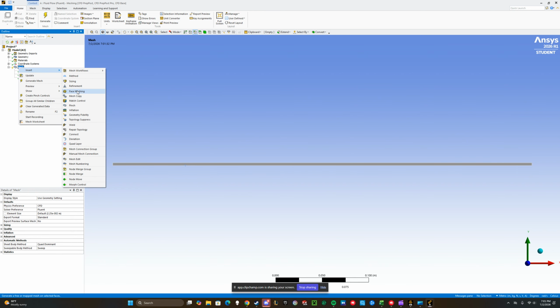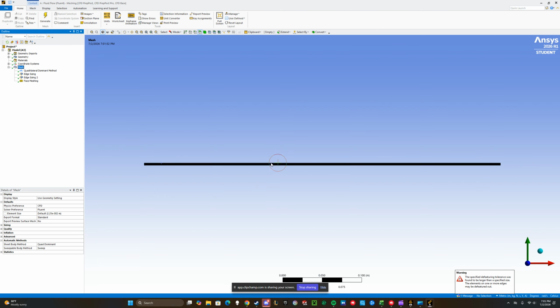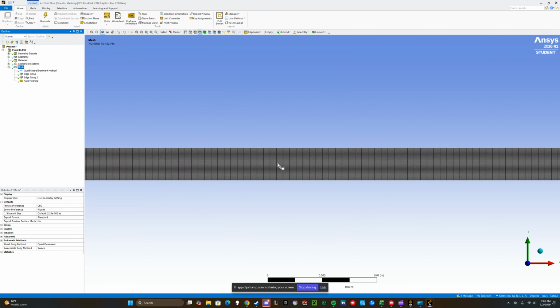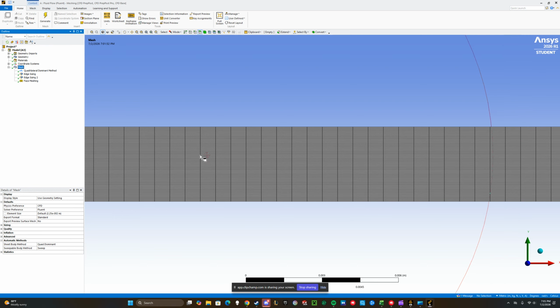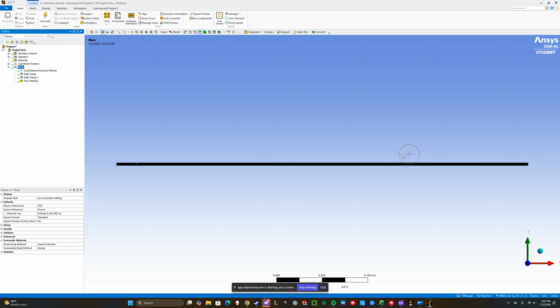And so we need one more. This one would be a face mesh, where all we need to do is select the face and click apply. That will do everything we need to do for this one. Nothing further is needed. Then we hit generate. And we know it should be correct if this mesh looks completely black and all these units look fairly uniform and rectangular. So that's correct. The start and end should also be like that if we were to zoom in. I'm fairly certain this is correct.